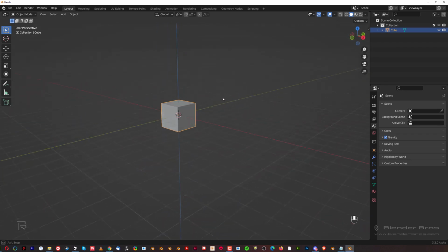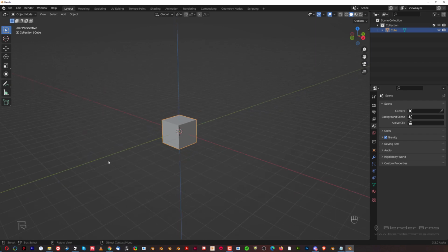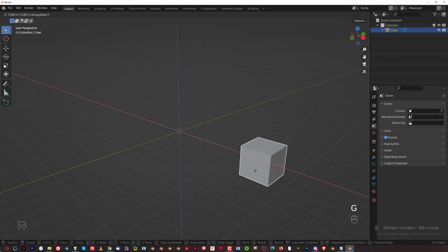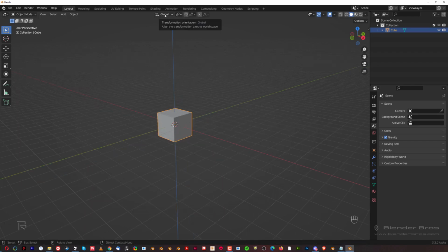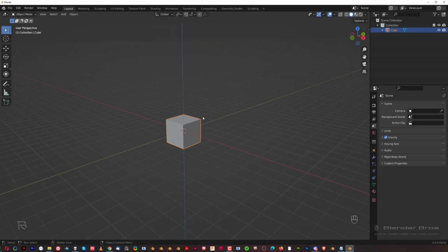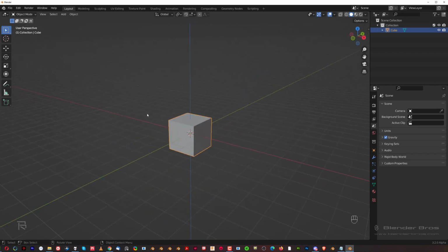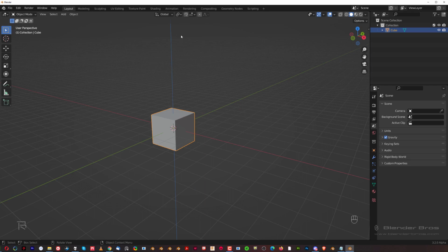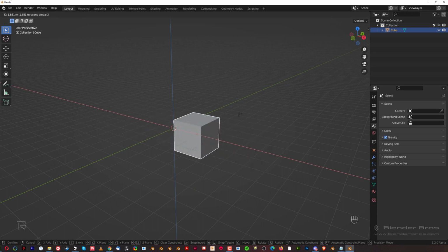These axes define the positioning of your model in 3D space. So when I move an object, for example, I can move it on the Y, X, or Z: G then Y, X, or Z. Same with rotation, R then X, Y, Z, and scaling, S then X, Y, Z. This global transformation refers to the basic world orientation. So if I transform something, move it, scale it, etc., on a global axis, like global Z or global Y or global X, that's what it means.